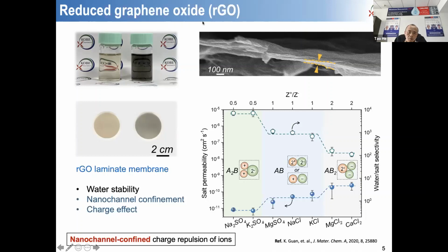Just following the question, does this mean the spacing you design in your membrane is quite large? So it's slightly larger than the hydration radius of magnesium ions? Yes, I think the mechanism, the hydrated magnesium ions can dehydrate. If the size is too large, it can dehydrate to remove some water shells to enter this pore size. And I think the size is not enough to establish steric hindrance towards hydrated ions. It can only enhance the energy barrier for the ion transport.